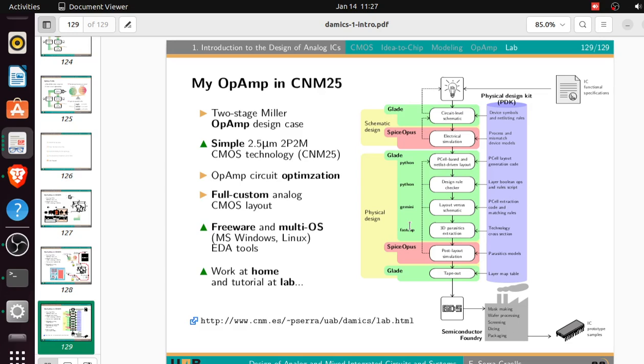You just want to make a MOSFET, but as part of what you're designing, you get capacitances and also resistance. From the device physics you understand why. So for that given layout you've done, you get to see how much of those parasitics you have, and that way you know if what you've laid out is really going to work well.